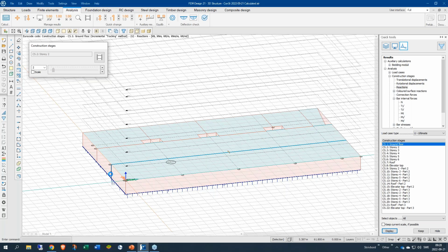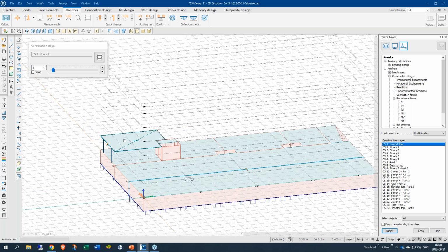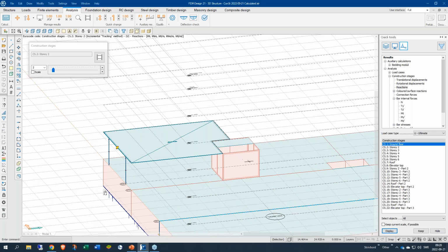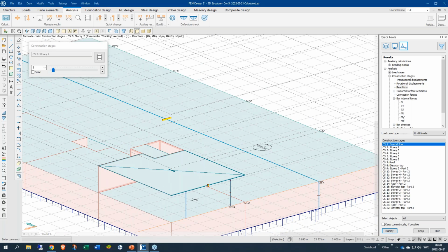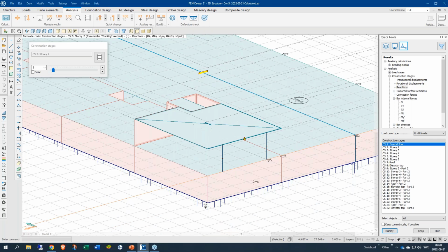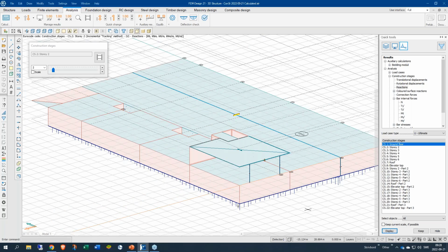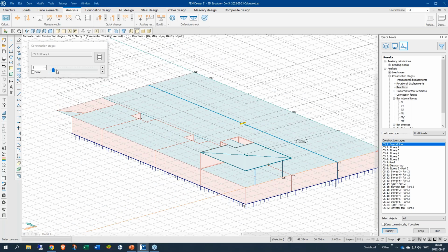And when I've now applied the first structure here, where they will be placing the walls and the hollow core plates, the beams and the columns and so on, there will be a distribution of the loads that will be acting differently compared to if we just placed or built the whole structure and just made a load takedown from that.